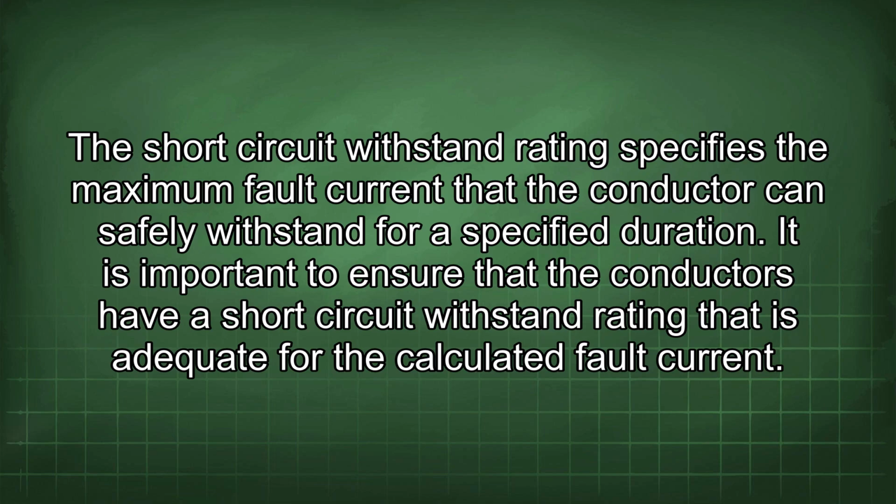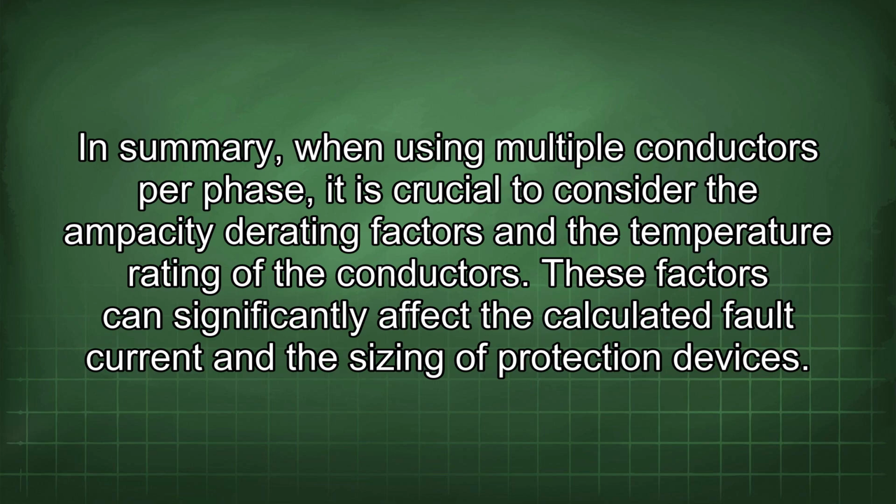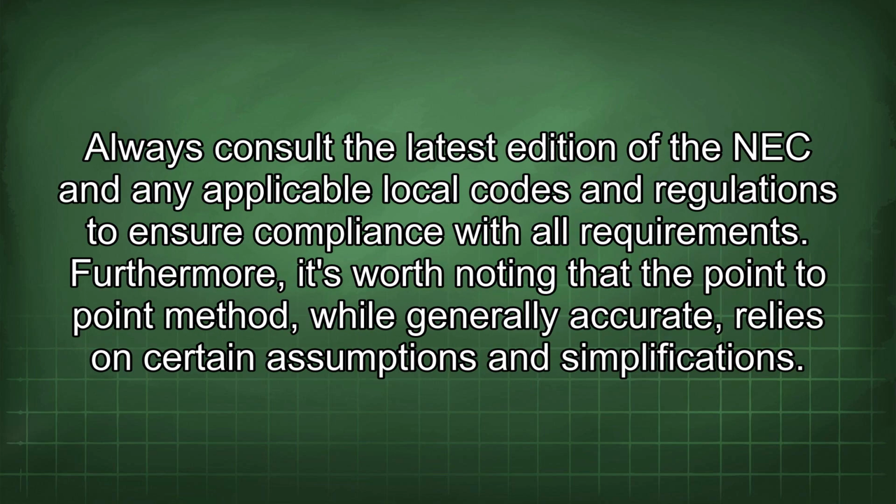It is important to ensure that the conductors have a short circuit withstand rating that is adequate for the calculated fault current. In summary, when using multiple conductors per phase, it is crucial to consider the ampacity derating factors and the temperature rating of the conductors. These factors can significantly affect the calculated fault current and the sizing of protection devices. Always consult the latest edition of the NEC and any applicable local codes and regulations to ensure compliance with all requirements.